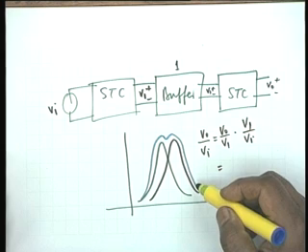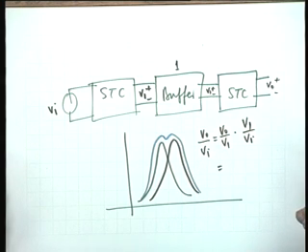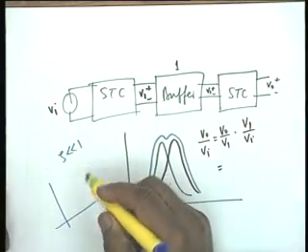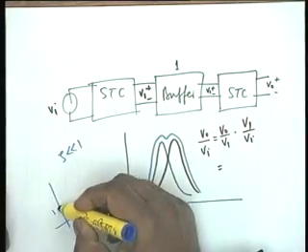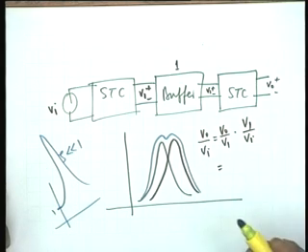Okay. Suppose, yeah. So the last stage was also similar. May not be. It is not similar because the resonance frequencies are different. No, sir, the capacitor and resistor, if it took the output in a double tune circuit across the resistor and capacitor. Okay, it will either be a low pass, high pass or band pass, but zeta should be much less compared to 1, so that even if it is low pass, even if it starts from 1, there is a high peak. But if individual of both was low pass, yeah, two maxima. Dip in between.